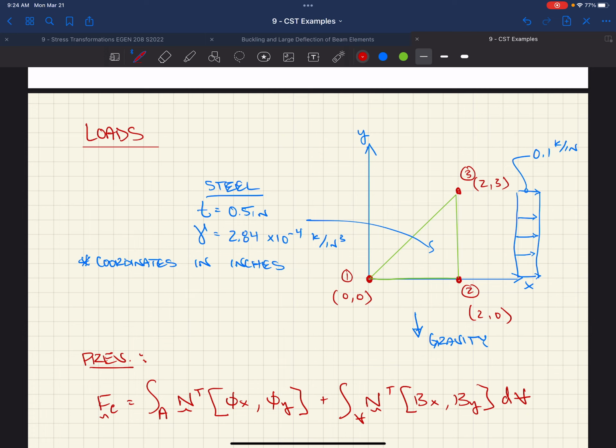So this wall just stops at the floor, doesn't go anymore. So we have to take this load out of this wall somehow and apply it into this floor system. And so instead of a uniform load over an edge, perpendicular to the edge, it might be parallel to the edge. It might actually start acting in the y direction, and it might just be a line load from nodes 2 to 3. So we would apply that.